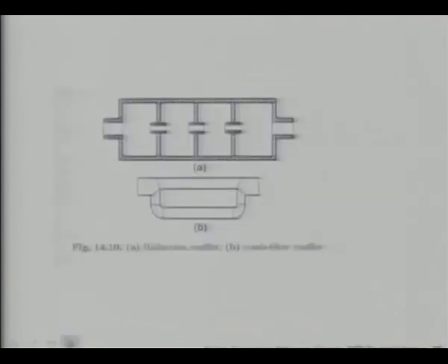This is another one. So in the analysis which we did, that muffler is tuned to a particular frequency, right? So as I shift from that frequency, slowly the transmission loss will not be as great as I would like it to be. If I am very far away and sin k2L equals 0, then that whole purpose is lost.